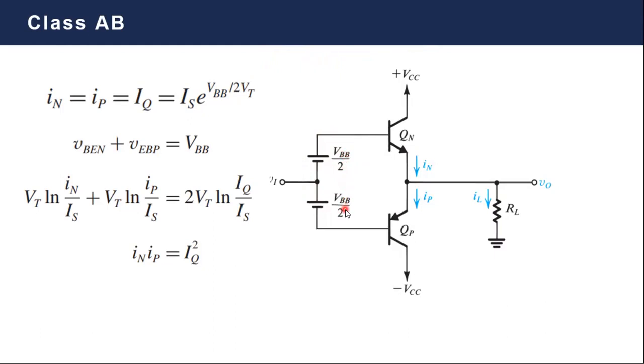Second, you don't have any possibility to tune this voltage. The voltage here between these two points is the base-to-base voltage, that's why we call it VBB. This VBB will be kept constant all the time. It's not controllable. So first, you assume a symmetry or a match between these two points. Second, you don't have the privilege of controlling it.